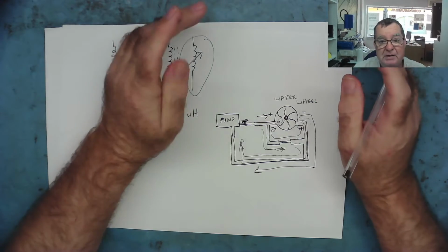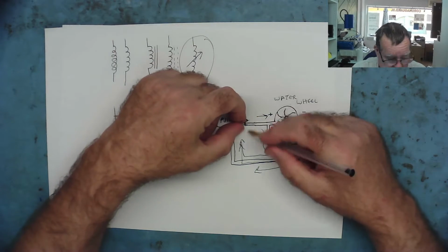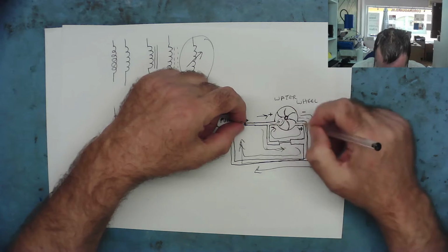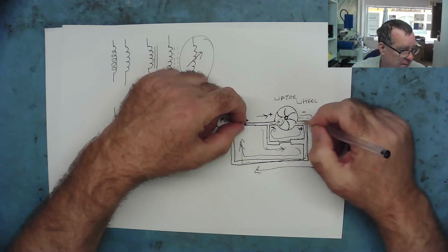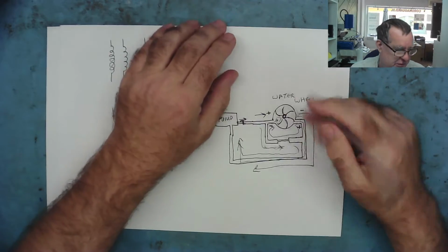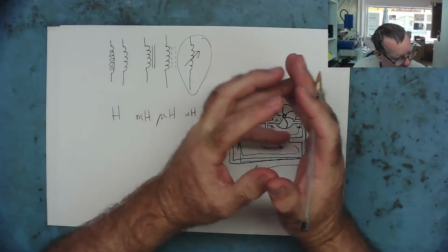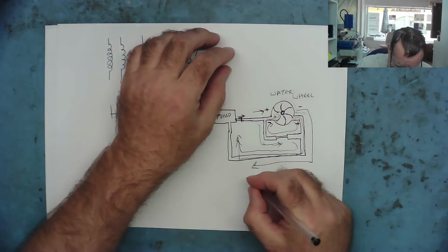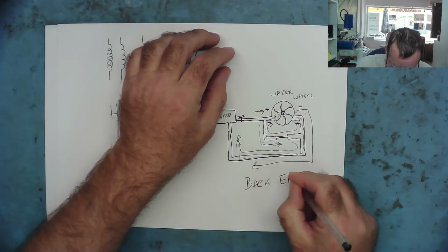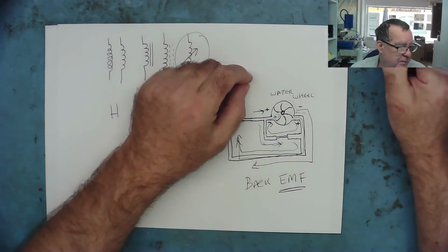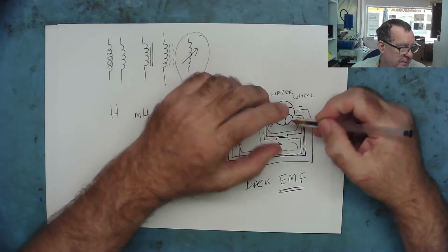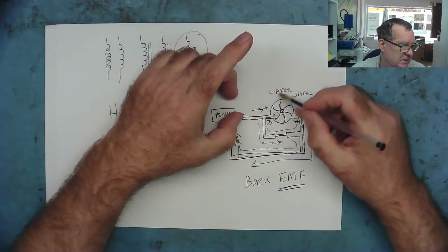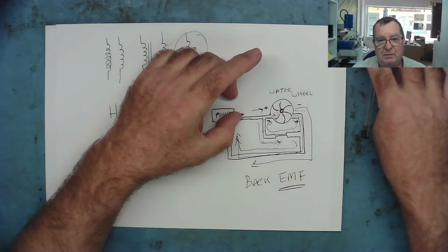And that same thing applies in the electrical circuitry. So when you suddenly interrupt the flow of current through an inductor, the inductor will continue to push current through the load because it has inertia. It has to slow down effectively. The magnetic field has to collapse, and during that time, the polarity across the inductor reverses. And that has a name, and it's called back EMF. This can be important in circuits because this reversal of polarity can affect the device that's switching this on and off, especially if that's a transistor, for example.